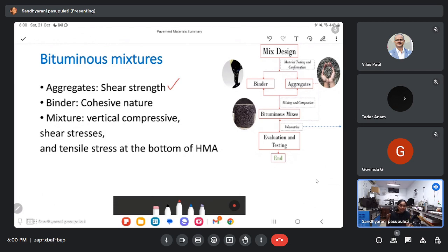Based upon the shear strength of the aggregates, if the aggregates are completely interlocked, they will not fail so quickly. So aggregates provide the main shear strength. Though aggregates are interlocked and provide high shear strength, there should be some binding method in between the aggregates to keep them together. The complementary bonus strength is provided by the binder. But as far as asphalt mixtures are concerned, shear strength is provided by the aggregates and is supported by the binder.